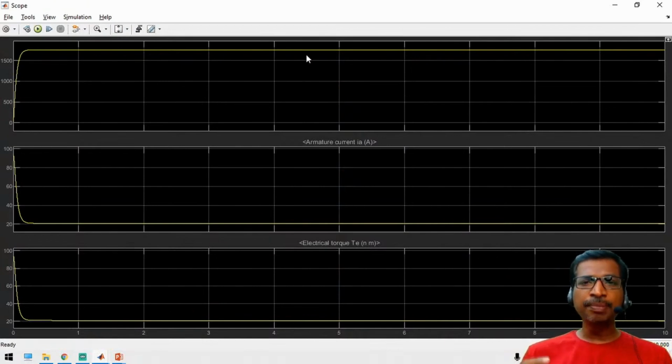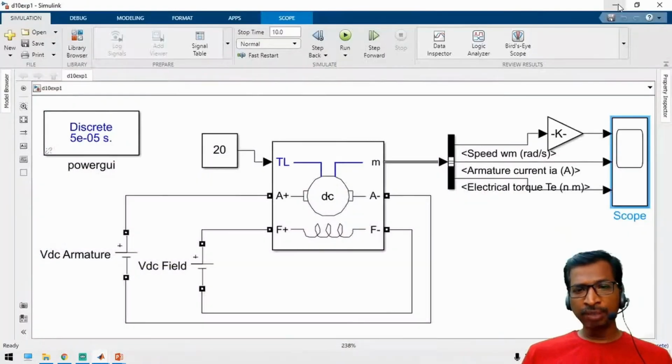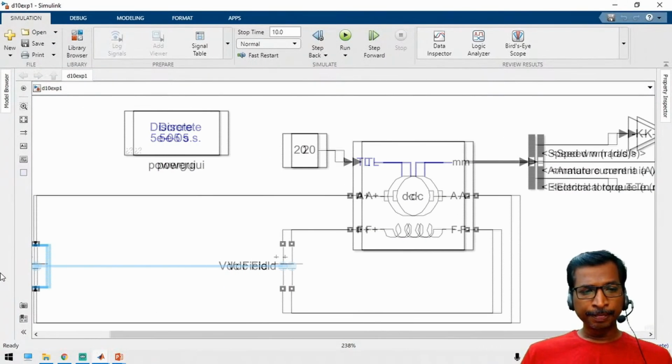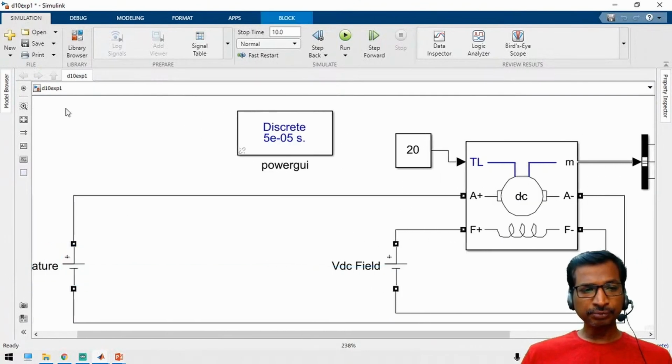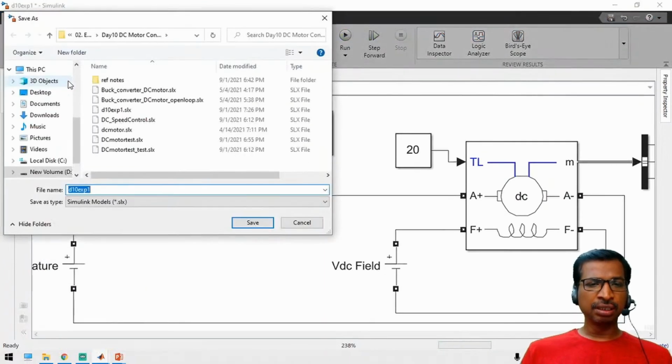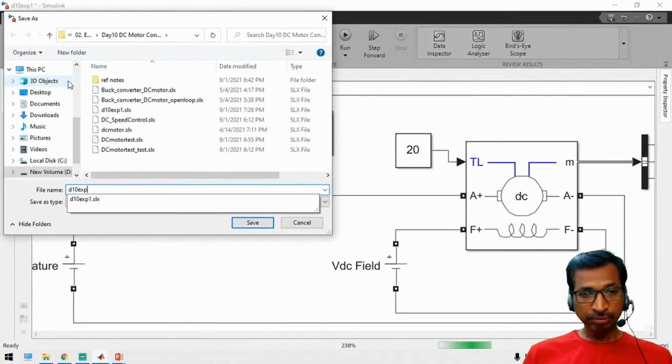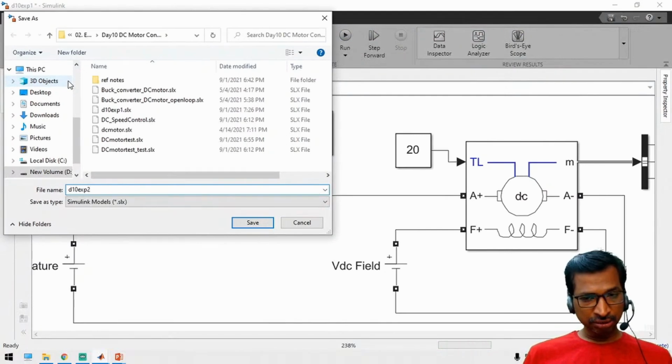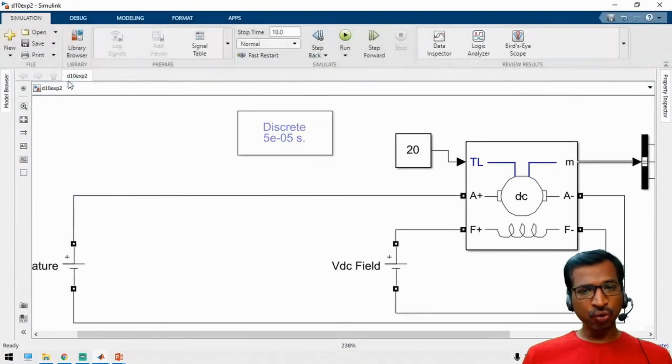So now we have to implement the DC motor speed control mechanisms. To implement the speed control mechanism, what do we have to do? For that, you can have a single quadrant chopper and then a 4 quadrant chopper.